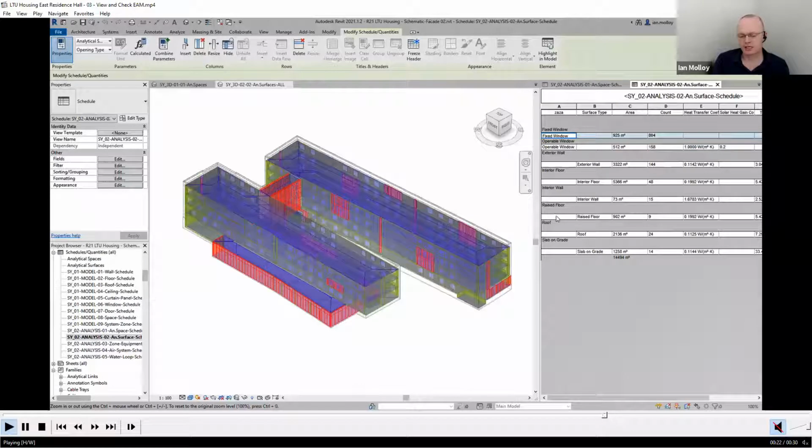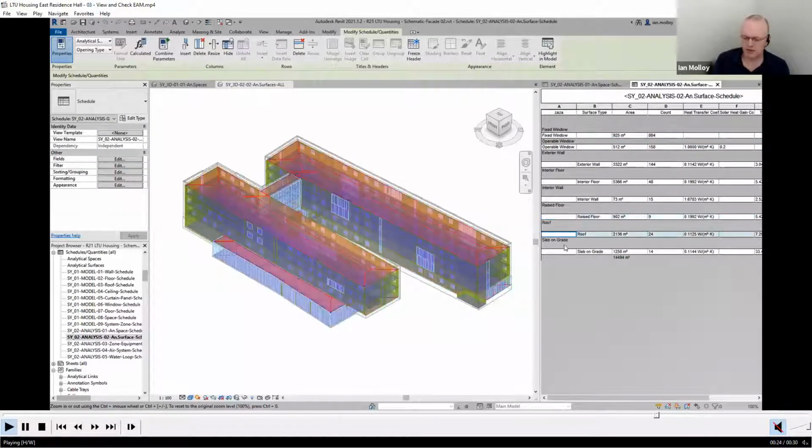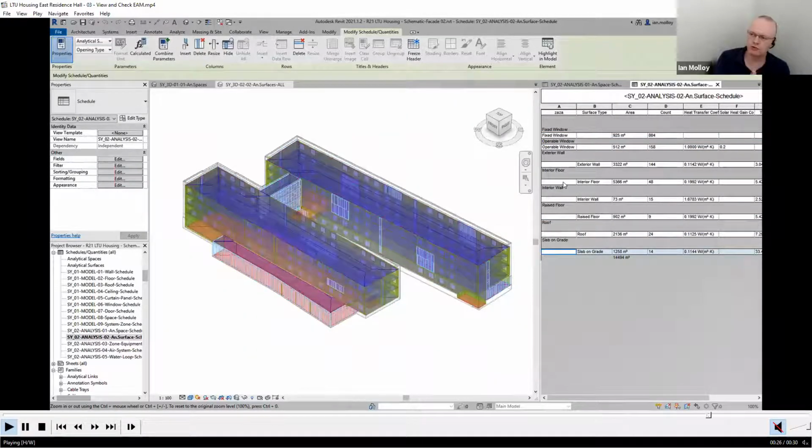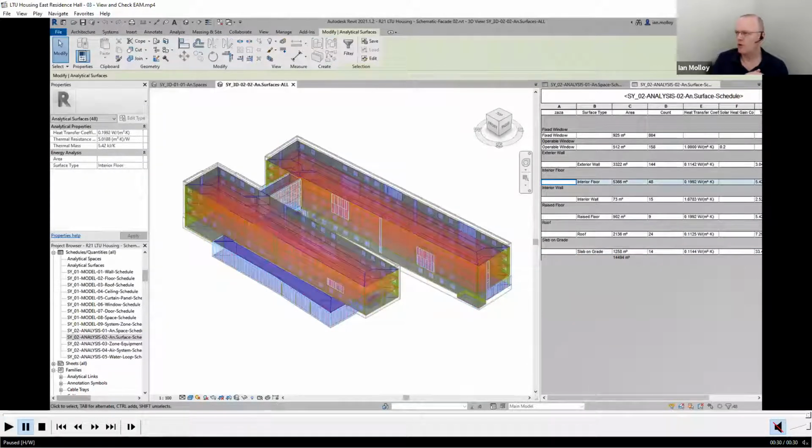So what you'll see here are the analytical spaces. Where you've got walls, floors, roofs, and windows in Revit, they may not actually be modeled or used as such. Walls or floors can sometimes be used as roadway and things like that, right? So how do you differentiate that? What this does is a pretty intelligent translation of that, and it's able to interpret when a wall is interior versus exterior, regardless of its function setting and so on in Revit. It basically does a sort of 3D scan of the building and interprets where things are.